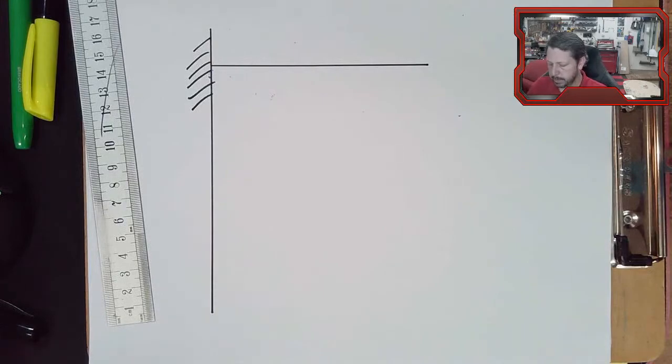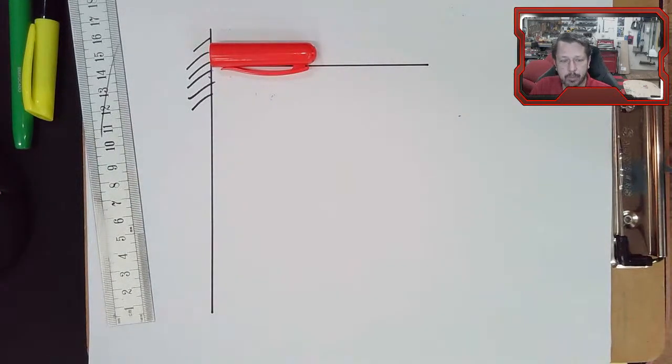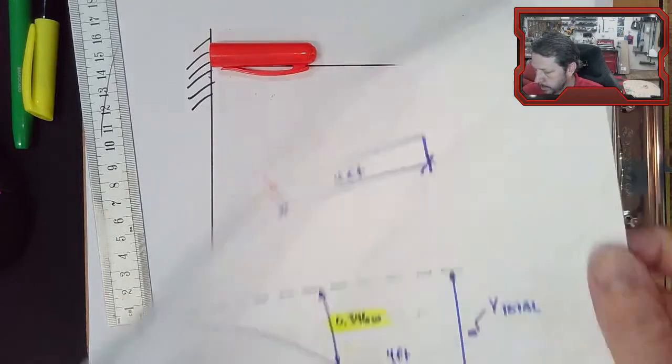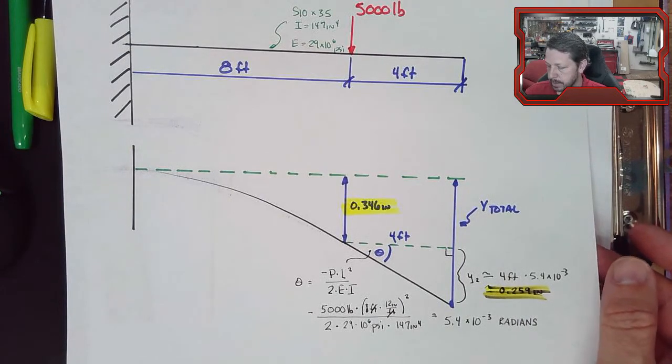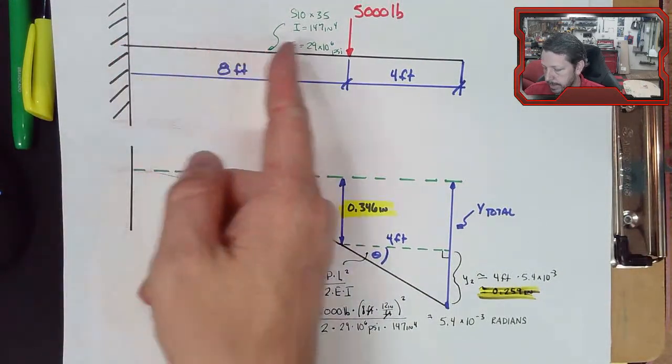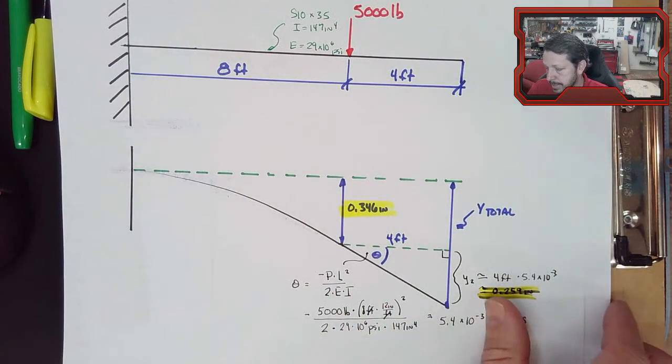All right, cantilever beam, and it's going to have a distributed load. Now, if the distributed load was right here, for instance, on the wall out to some point, that is basically the one we just did earlier. Basically this, except with case 2 equations. So you have the distributed load from here out to wherever it ends, and then you do this thing to get to the rest of the beam. So that's not too bad.